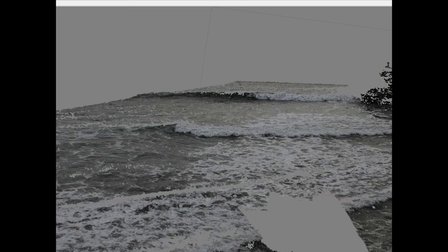In terms of where we put them, we try not to require too many photos to be unsupported by them. So we try and get them no more than like 5 photos apart, which ends up being a couple hundred meters in our case. We then distribute them around the edges of our area and along the topography. So we get them as low on the beach as we can and as high on the dune as we can, and places in between. So we're sampling vertically and horizontally and trying to capture it.